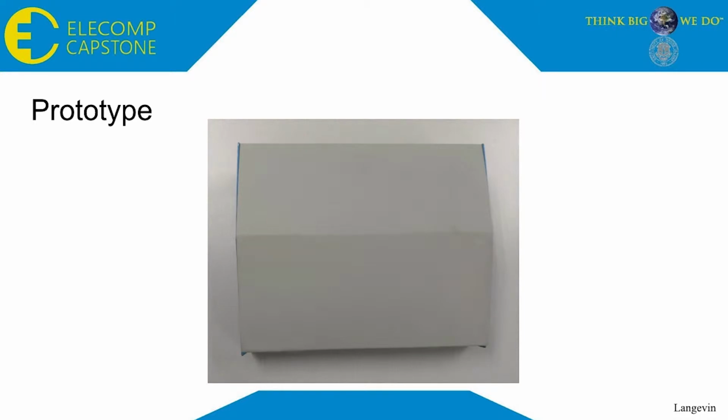So this is the prototype that we built and designed. This is a Hammond board, which is typical in a testing environment. So this is how it was put together. We have the 24-volt AC power coming from the HVAC unit. The 7 individual thermostat controls coming in from the thermostat.